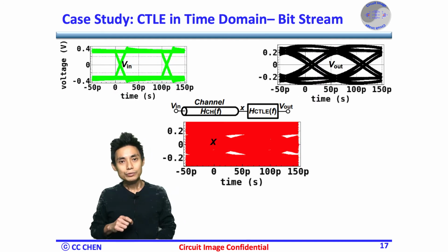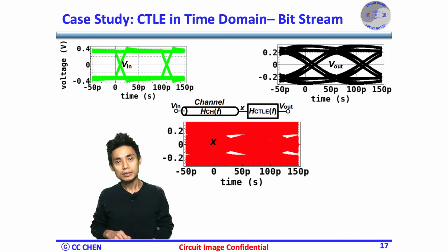In the last view of the time domain, the bitstream response eye images should be verified for the CTLE's performance. Usually, an eye diagram will be evaluated through tons of bit overlap to check the eye width for the timing margin and the eye height for the voltage margin.